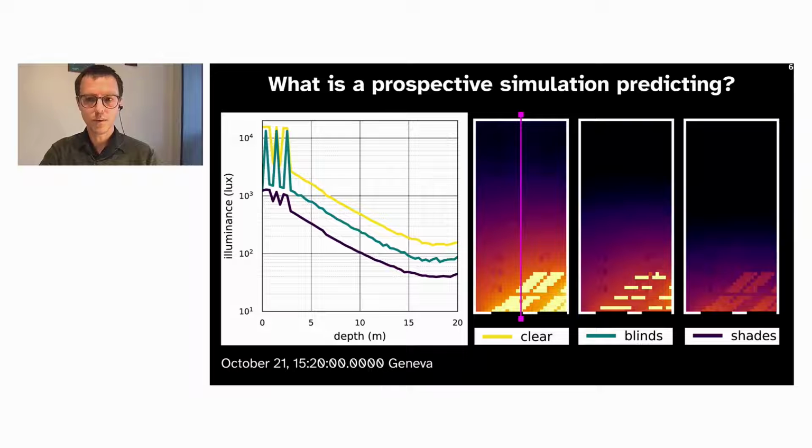Given this example of a deep room with windows only on the south elevation, we can imagine generalizing from the plans on the right to the single section on the left. While the section will vary across the space from east to west, it will do so fairly uniformly between the three options shown here. Looking at the section, we can also see that a single point deeper in the space could just as effectively characterize these options, as the relative difference between the options beyond 5 meters is fairly constant.